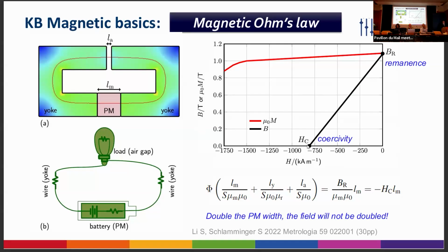It's typically a negative value, and with the minus, of course, this would be a positive number. If you write phi as B times S, the product of magnetic flux density and sectional area, then the S is gone, and you have B over mu, that is H. So you have H times the length integral equals minus Hc LM. That's Ampere's law, right?